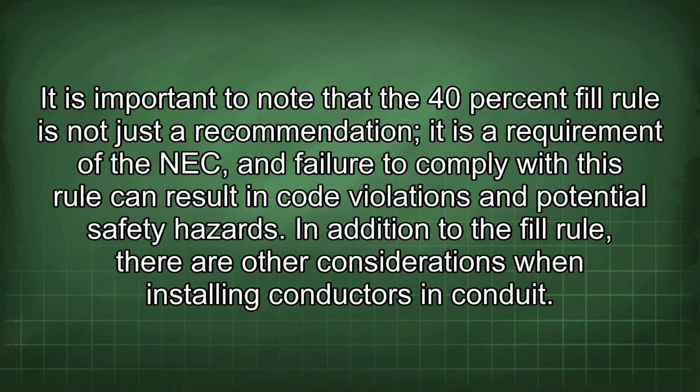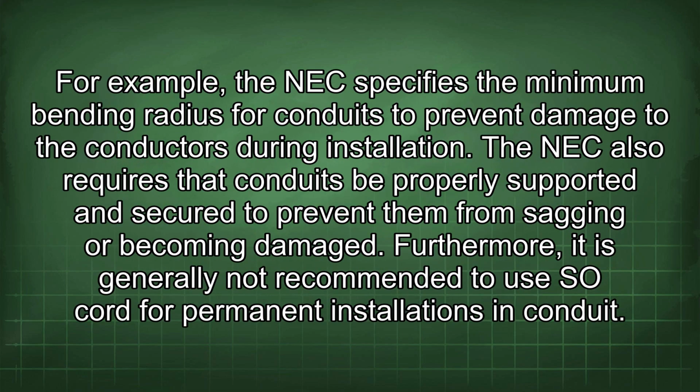In addition to the fill rule, there are other considerations when installing conductors in conduit. For example, the NEC specifies the minimum bending radius for conduits to prevent damage to the conductors during installation. The NEC also requires that conduits be properly supported and secured to prevent them from sagging or becoming damaged.